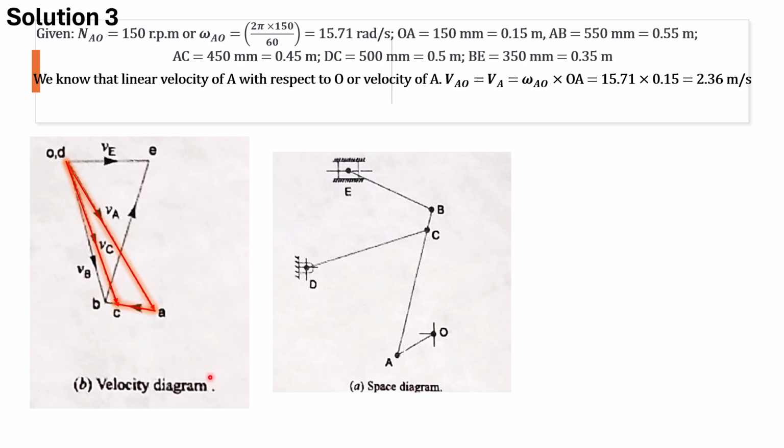Now we are able to get the point B using the ratio of AC over AB equals vector AC over vector AB. Once we do that, then we can now go ahead and get to the next link, which is link EB, and from the point B, we construct BE, which is perpendicular to the link EB in the direction shown.